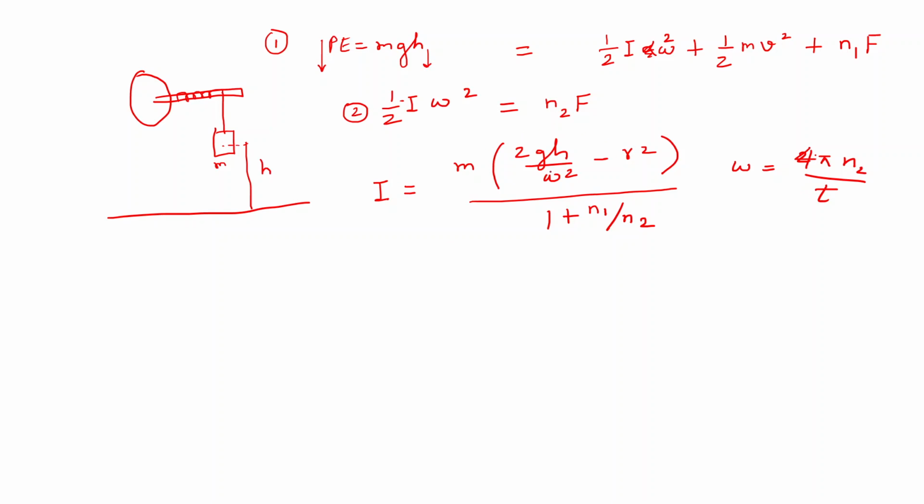And you know how the experiment has to be done, right? We need to take different masses, or basically we can change the mass and also the height, and we can keep on repeating this experiment. We need to note down the number of turns and the time after the mass detaches from the axle, and using those parameters we will finally calculate the moment of inertia, and we will take the average for getting a better value for this experiment. So this is the working formula for our experiment.